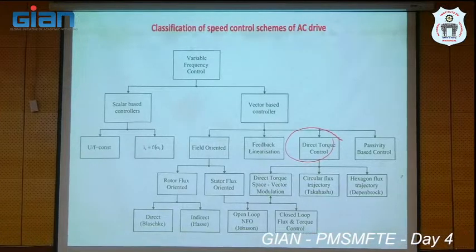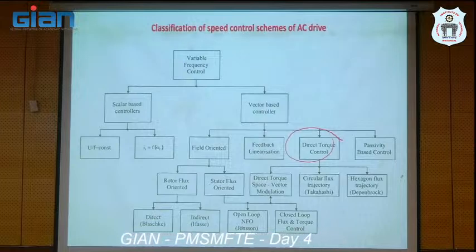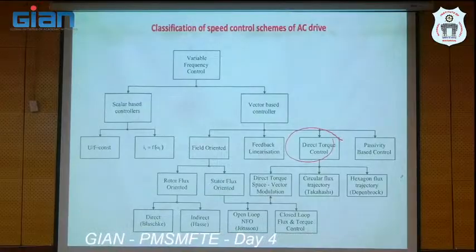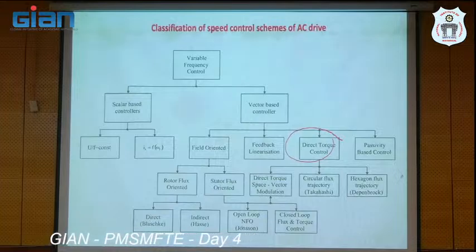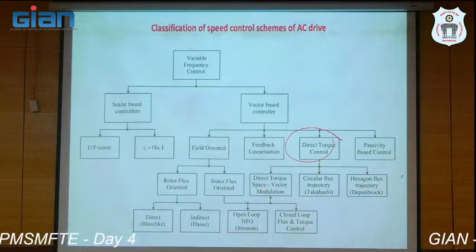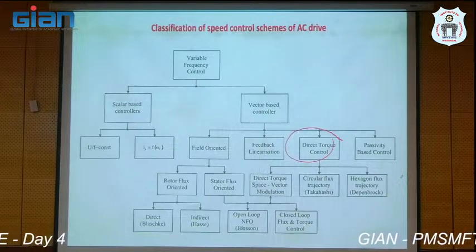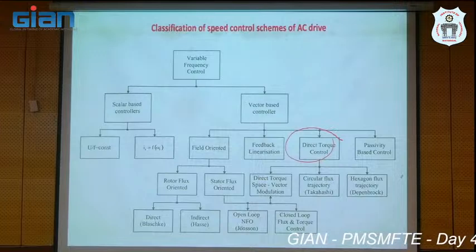So whatever parameters we take, with those parameters it will not give a sufficient delta calculation. The rotor flux position calculation will not be that accurate. That's why, if your system operates for a long time, the field orientation method will not work effectively. If the heating effect is very small, that is, the operation period is very short, you can go for field orientation.